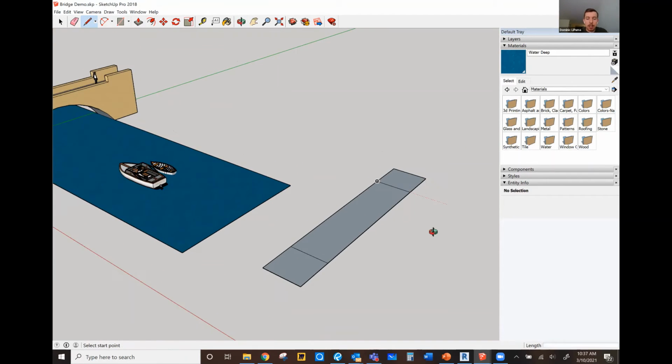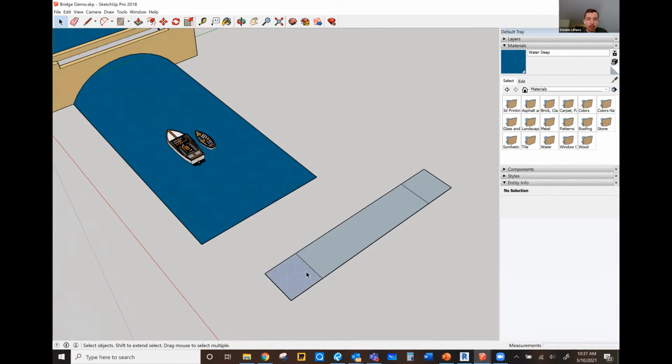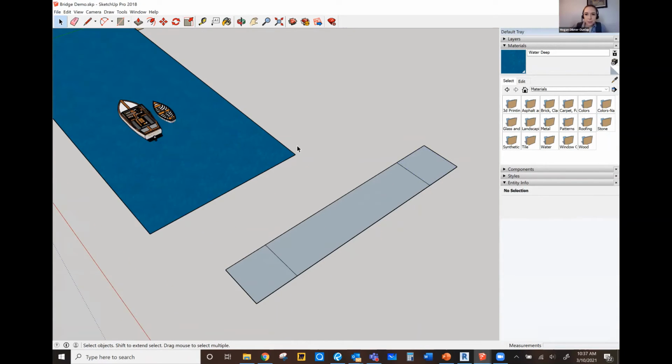Now we have two lines that are offset at 12 feet on either end. You'll see when I start to select these surfaces, it divides it into 3 different surfaces based on where those lines are. Next is using the paintbrush, color each end of the rectangle.